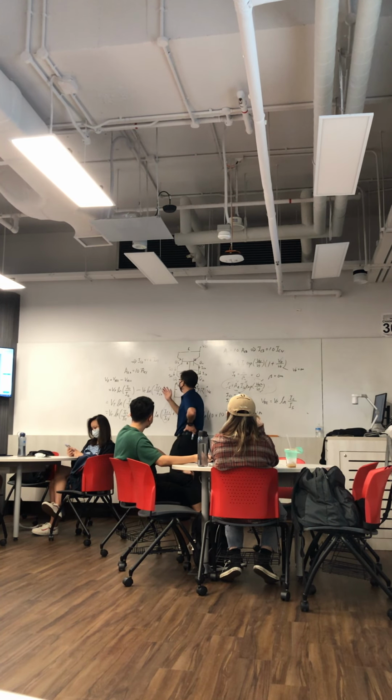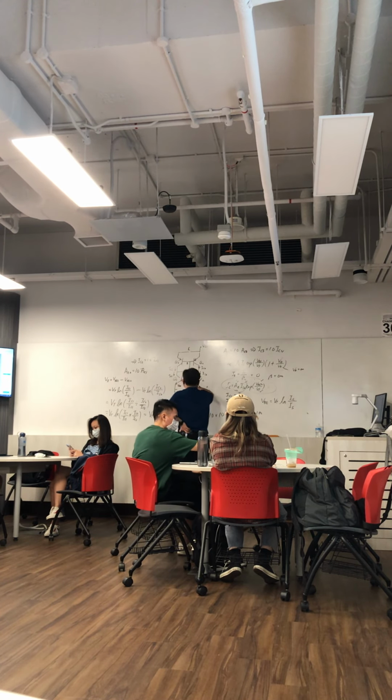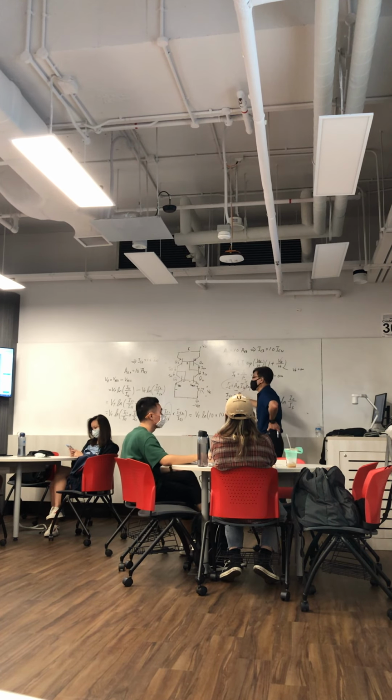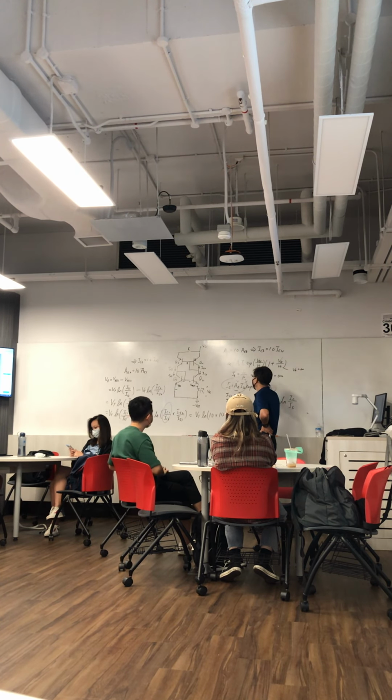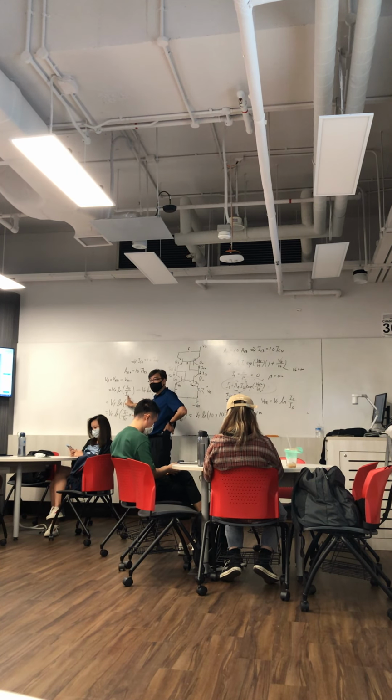So all you need to do then is solve for the voltage difference, which is actually the voltage across this, in terms of IC and IS, which is the logarithmic form here.